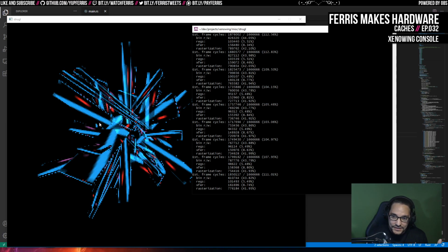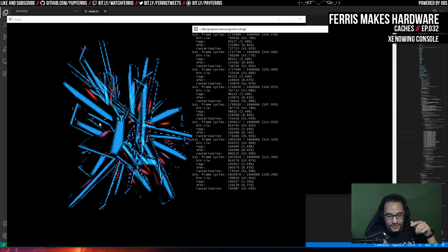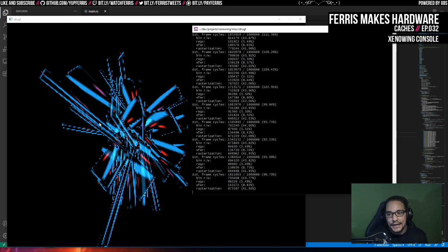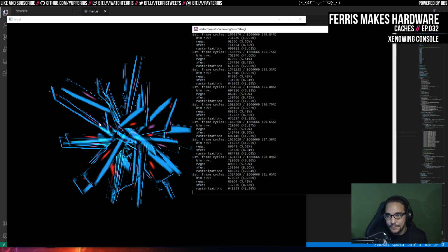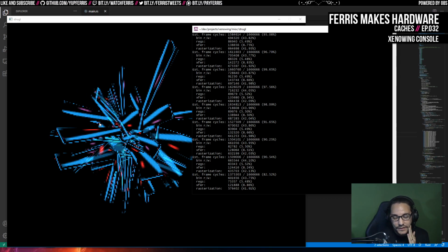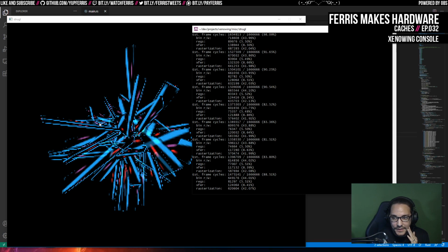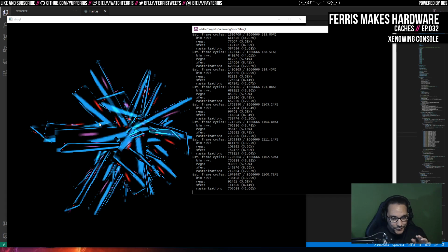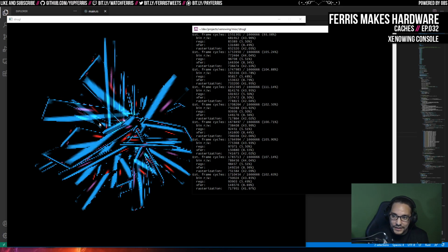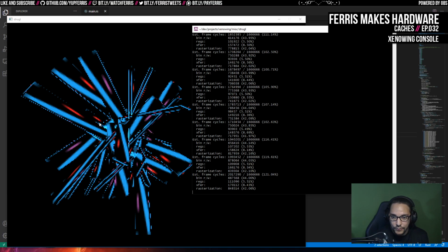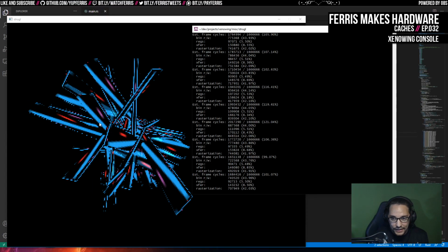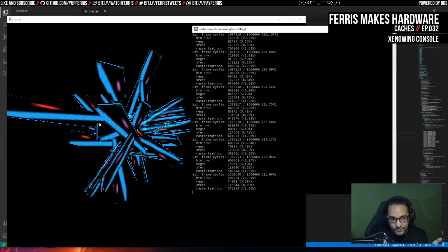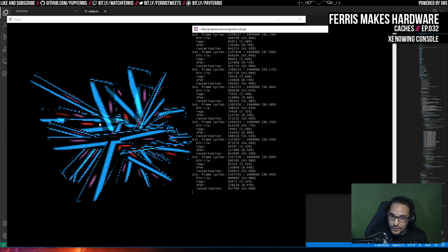So that does complicate things a bit, because we need to add another data path so that the rasterizer can actually go and fetch that data if it has to. And also, we may need to stall the pixel pipeline. So it's going to make things a bit more complicated, but I think ultimately it's going to be more performant. And that way we can also make that texture cache a bit smaller, because it doesn't always have to hold the entire texture. And more importantly, we save a lot of bandwidth overall by not moving more texture memory than we have to, and not moving the color and depth data in and out of the tiles more than we have to, ideally. So I think that's going to be really good.